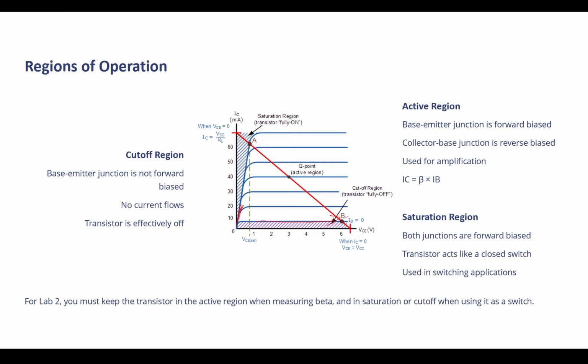Not exactly true, but approximately the same current. And when you are saturating that channel, again like the MOSFET, then you're capping your current. It doesn't matter what the voltage between the collector and emitter is, your current is going to be the same amount of current. Is that clear? Are we good on that?